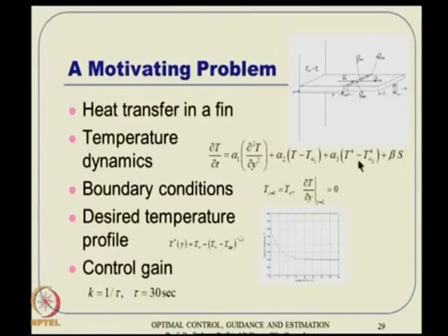There is a fin here, there is heat transfer here, and we are assuming all sorts of heat transfer, that means conduction, convection and radiation, and there is a source which is coming through the wall. So, this kind of modeling will excite nonlinear behavior also. Depending on the situation, how much nonlinearity will depend on the alpha 3 quantity. Ultimately, what we really need is a steady state profile, something like this. Obviously, there is a root. This is something like a fin for heat dissipation.